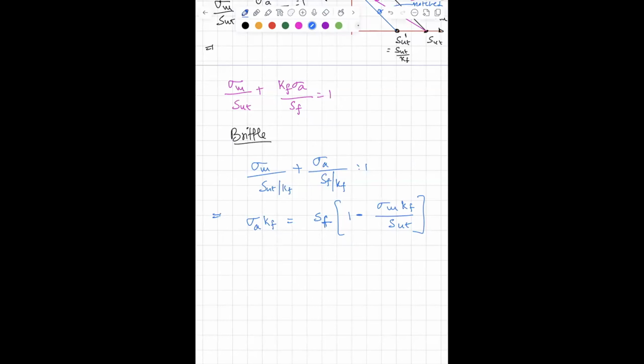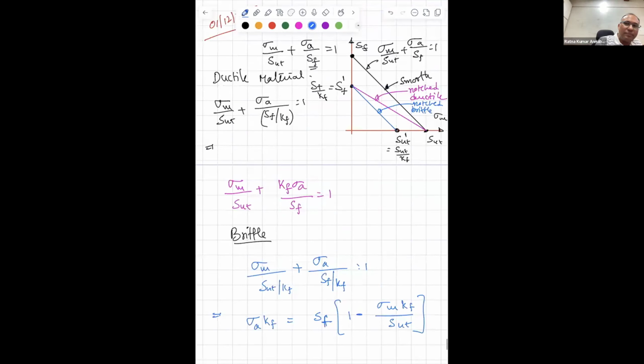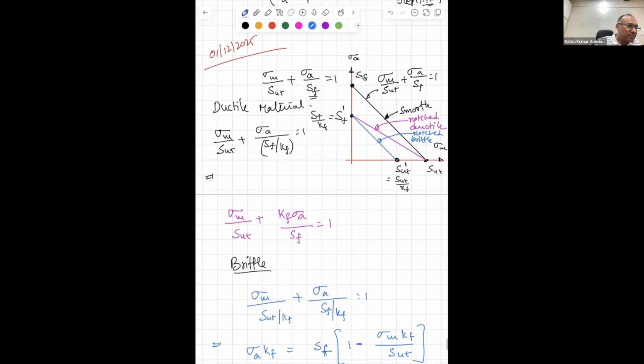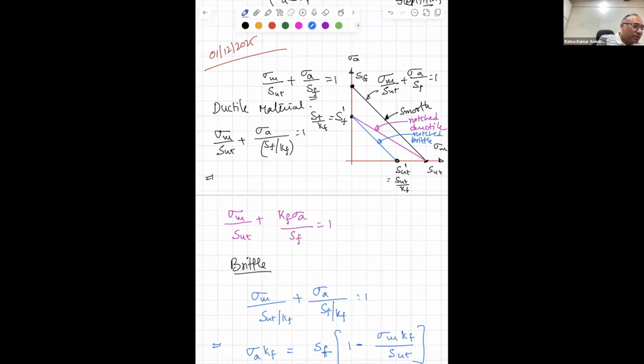Sir, I just joined late actually. So why are we applying the fatigue stress concentration factor to the mean stress only for brittle material, sir? Because in the case of mean stress, if it is a ductile material, by the time the stress reaches SUT, there will always be some plastic deformation.